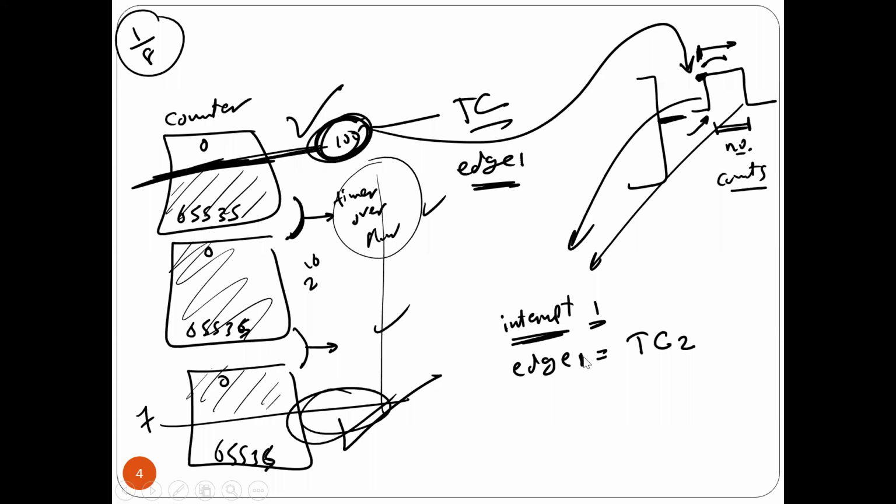Number 2, because I have to enable timer interrupts. Okay, because I want to count how many interrupts should happen from here to here. So, okay, makes sense. So I'm going to enable timer interrupts from here once in the first interrupt. So once I receive the first interrupt, I'm going to enable timer interrupts to count how many overflows I have.